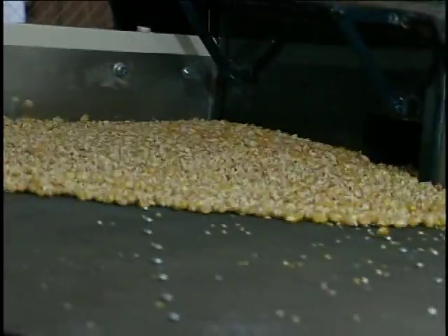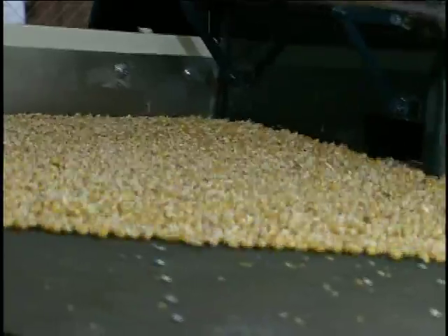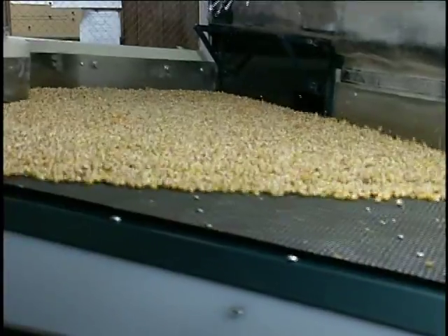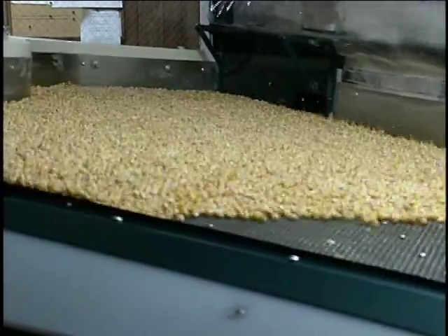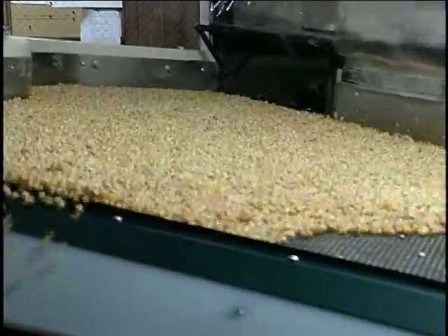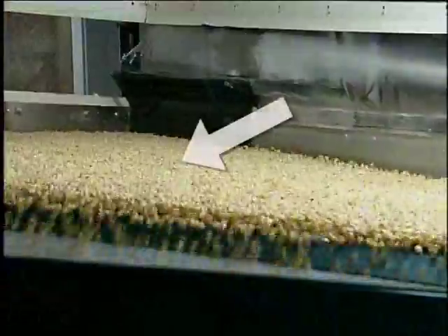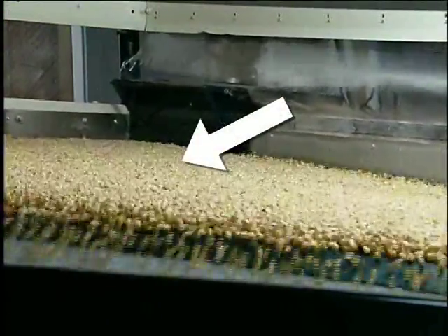The material should flow out rapidly to begin filling the deck. We have found that an initial opening of 1/2 to 3/4 of an inch wide is a good starting point. If the opening is too wide, however, then the material will tend to splash out onto the deck, and this condition should be avoided. Once the product starts flowing over the deck, observe its behavior in the stratification zone directly in front of the feeder.